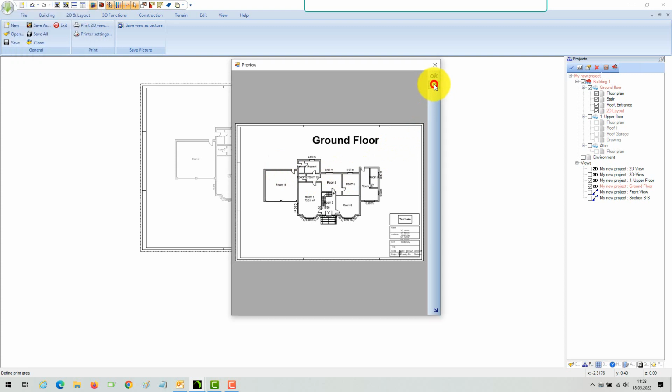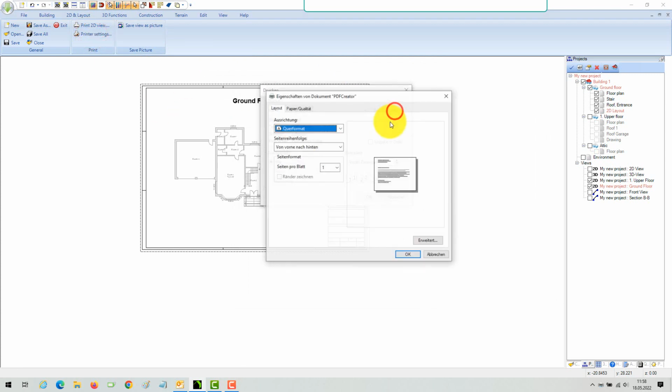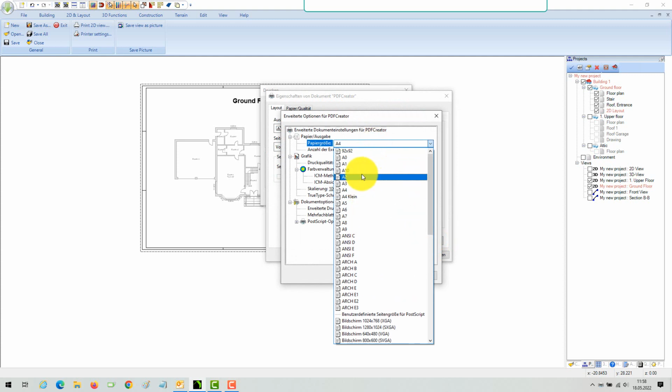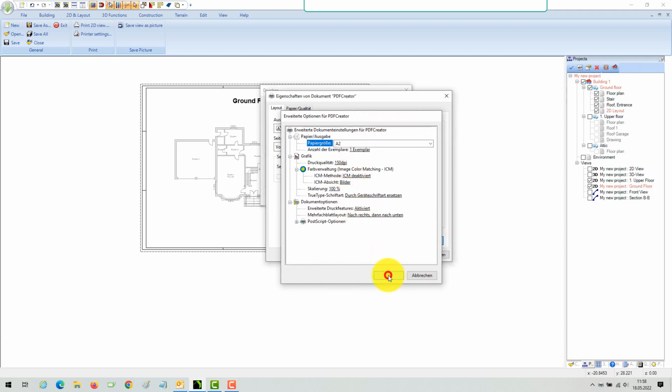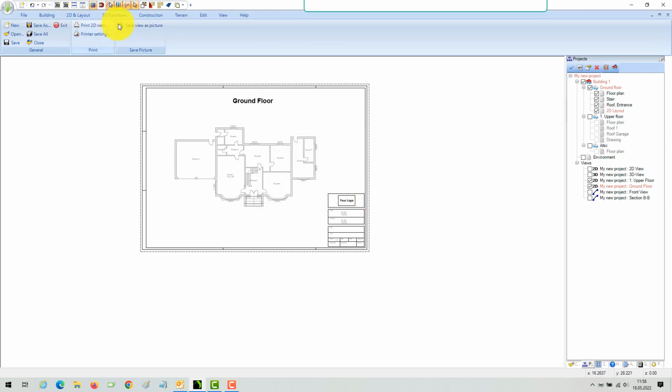You can skip the cursor with Escape. Now the software scales everything down in order to draw everything on A4. As a consequence, the scale is then lost and undefined, which is not intended in most cases. Set the paper format to A2 and start printing again. As you can see, there is no cursor preview because the paper size is big enough for the drawing content.